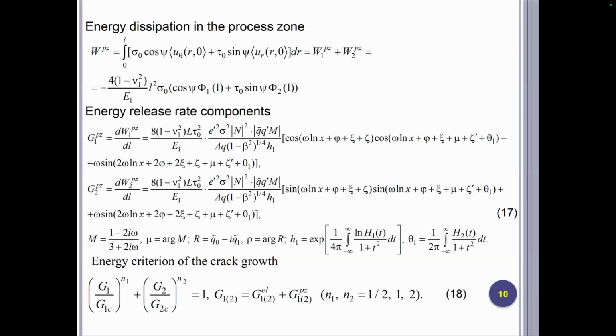It is a simple quadratic equation for the opening displacement criterion. Delta n and delta tau are the critical values of the opening displacement. It is widely used to formulate criteria for the finite element method in terms of energy.